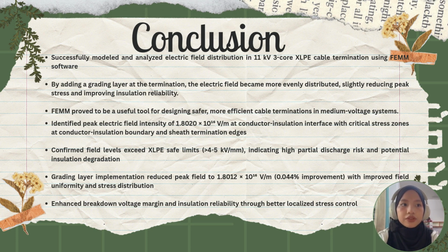Okay, so for the conclusion of this study, it successfully modeled and analyzed the electric field distribution in an 11 kV 3-core XLPE cable using FEMM software. By adding a grading layer at the termination, the electric field becomes more evenly distributed, slightly reducing peak stress and improving the insulation reliability. FEMM also proved to be a useful tool to design a better and more efficient cable termination in medium voltage systems.